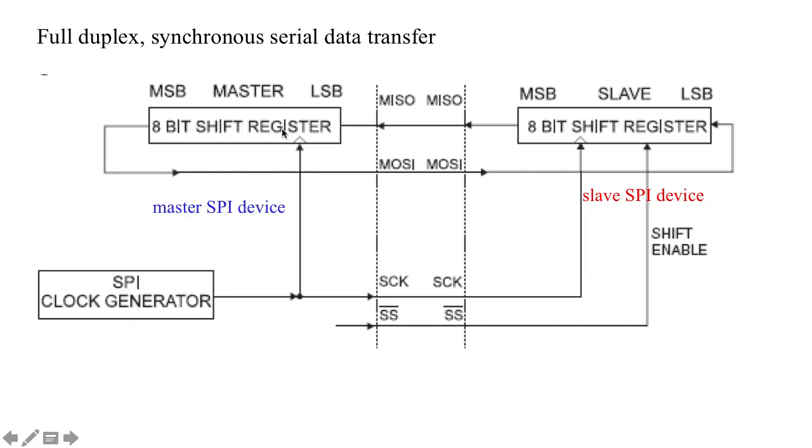So to recap, we have the SPI acting like one shift register, shifting into another, and the slave responding on a serial port using the MOSI MISO chain. Serial clock all comes from an SPI clock generator, and the SPI clock generator gets its clock by dividing down the system clock.